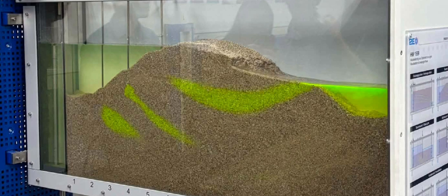Shaping the profile. Use a rigid trapezoidal template to trim the sand into a standardized earth dam profile, creating fixed upstream and downstream slope angles. A common configuration includes an internal horizontal sand filter or toe drain at the downstream base to prevent sloughing.